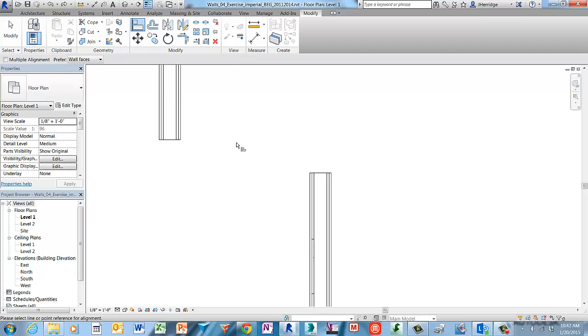Now let's take another look at creating alignment with the lower wall. So in this case, I'm choosing the left edge of the right-hand wall, and then I'm choosing the left face of the left wall, and then again applying the alignment constraint. So it doesn't matter which one's which, it's just which wall stays home and acts as the reference point for moving the other objects to that reference plane.